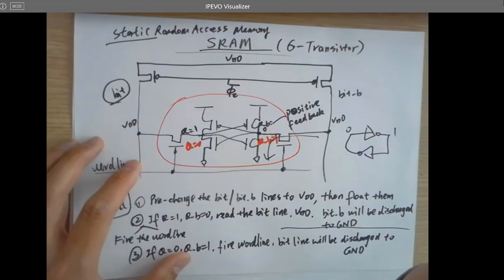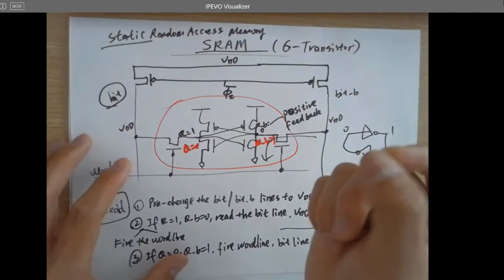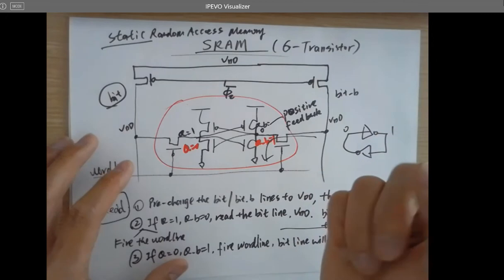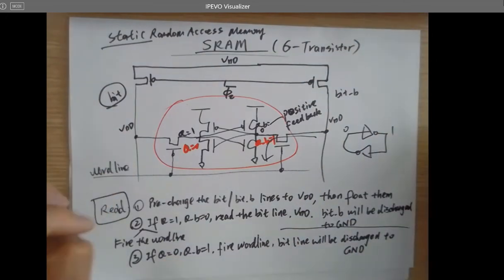So all the capacitors we've been using in the DRAM is only like 20 femtofarads, for example, and the metal wires running through all the circuits can be somewhere around 200 femtofarads. So who is actually storing the data, right? So that can be a problem. So we are going to talk about it really quickly.